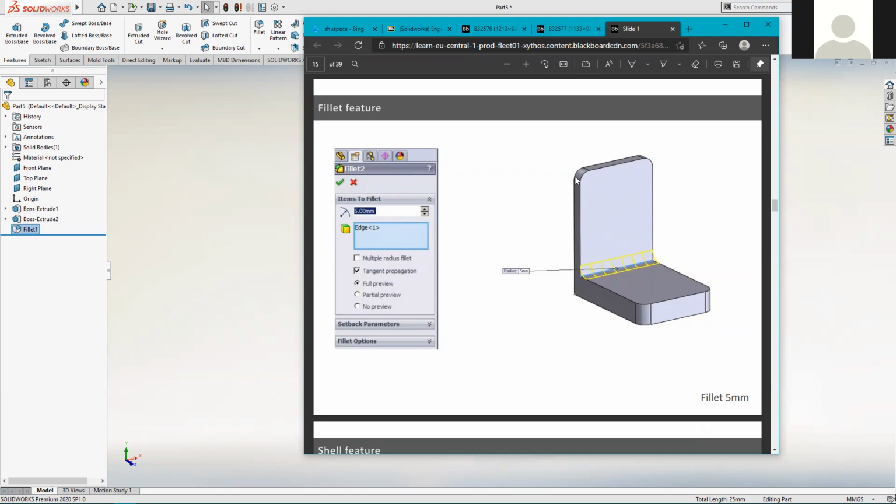And the logic that I came to the conclusion of was that within this design for this bracket, these edge ones on the outside of the part represent a different bit of the design, if you like. And it might be nice in the future to allow someone to vary the radius of curvature of this one that we're about to add separately to these ones. So even though they happen to be set to the same value currently, which is 5mm, we're just going to add a 5mm fillet there. In terms of the design, they represent two different things.